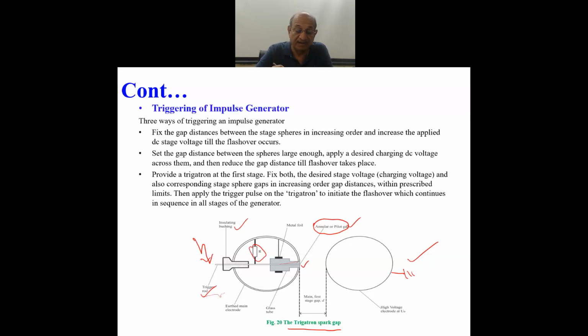And the most interesting thing is this device. What is this here? You have, in fact, an actual surface breakdown or surface discharge produced over the rod. We have produced surface discharge on glass plates, a very bright streamer, and even needle corona takes place as a surface discharge over a glass plate.